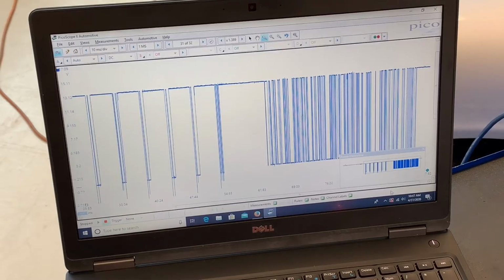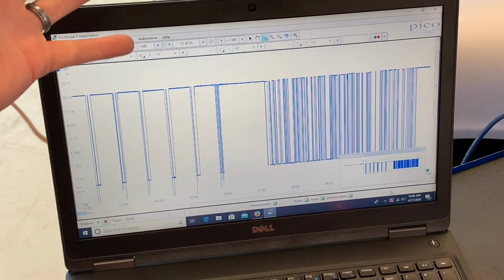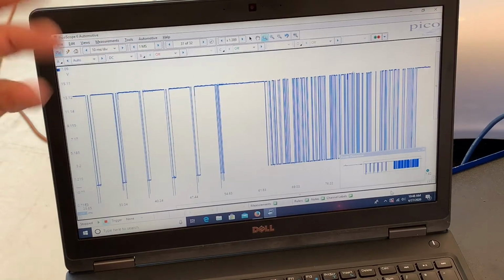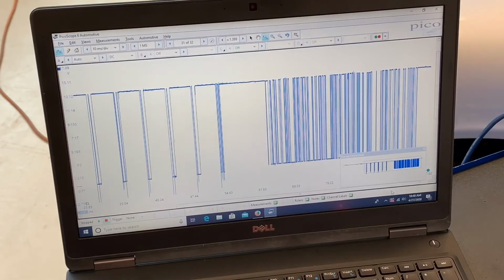Because those things help me understand basic electrical faults and occurrences, which typically are the things that bring me trouble. If this K-line signal was to get grounded or had some kind of resistive ground, it may change that voltage and bring it down. Those kinds of partial voltage changes are much more of an issue in CAN systems, and we'll look at how those are developed. Those are a bit different.